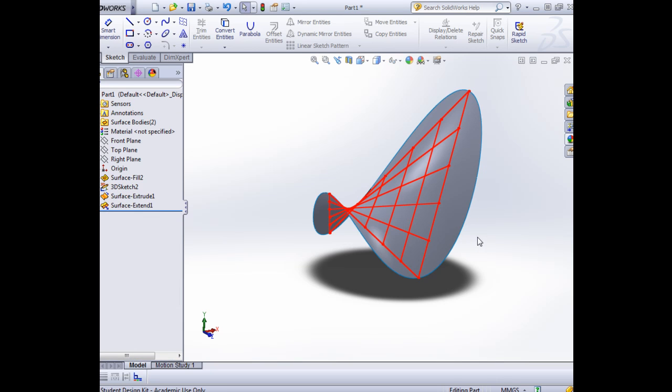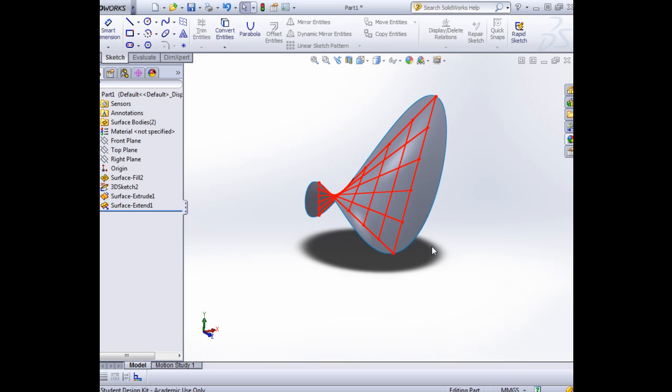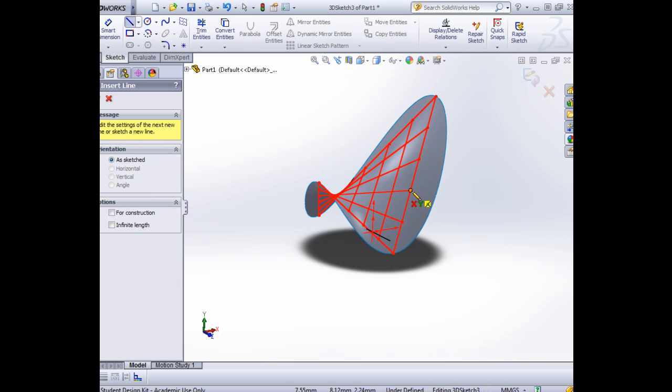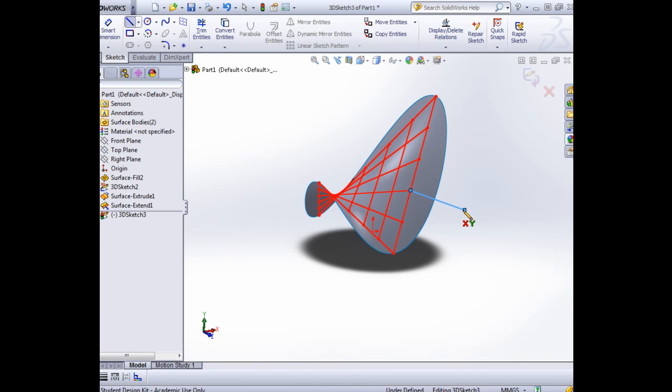When it didn't extend. Yeah. Can you extend them? You can. Actually, a very clever way to do that would be, it won't automatically extend it, but if you go back up to sketch, and 3D sketch, say you took a line from this point here. I want that line to come out, I want him to be what's known as collinear. Collinear means just an extension, at the same angle as this original guy here.